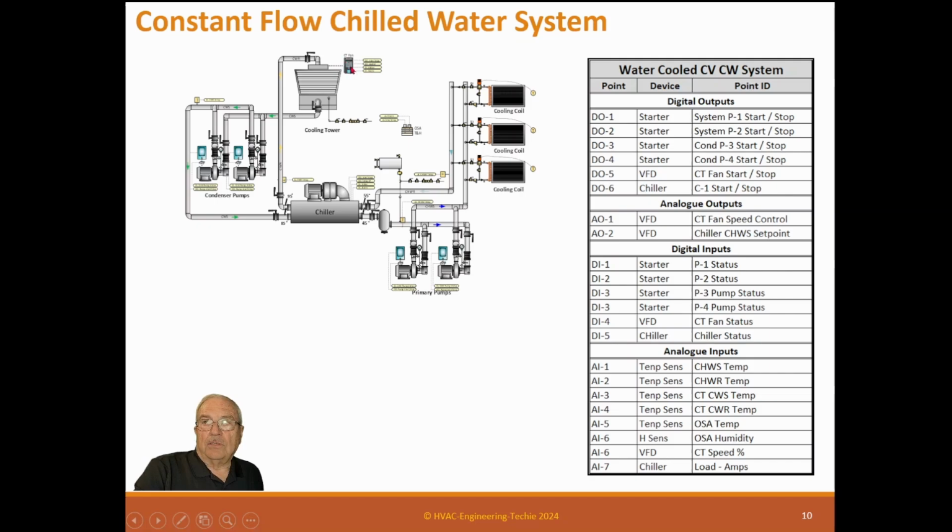You'll notice that the cooling tower has a VFD on it. And all cooling tower fans should have VFDs. You shouldn't even consider it without a VFD. And the reason is that they do 2 things. One is cooling towers very seldom run at full load all the time. So you can save enough energy to pay for it in about 18 months, 15 months. It got to where I stopped calculating them because I calculated every one, and they all came in excellent paybacks.